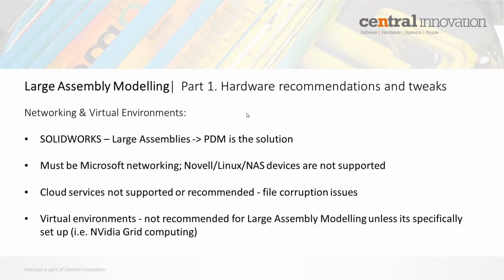it achieves two things. Firstly, you can store your files on a server location, but also PDM then brings that large assembly across locally onto your machine, so you can work at it at local speeds when you check it out. And then obviously once you've saved it and finished making new changes, you can check it back into the server and it can be safely stored there, and your IT can look after the backups of the files from there. PDM achieves a whole lot more than that, but in terms of large assembly use, it's certainly beneficial in that respect.